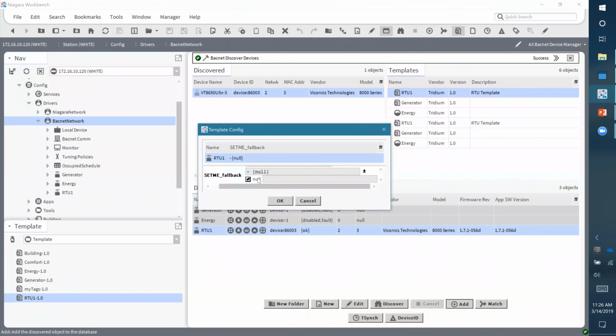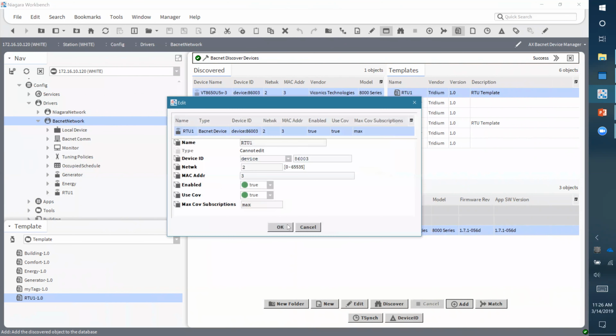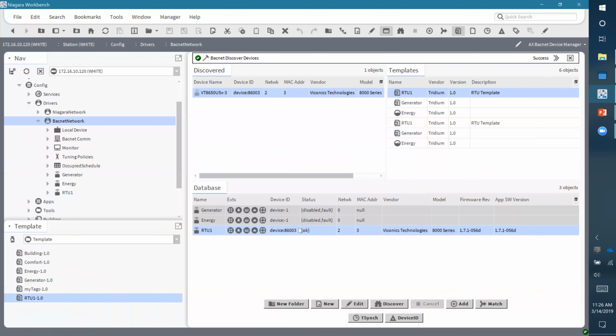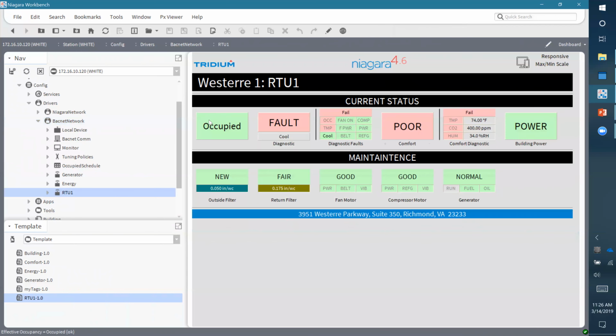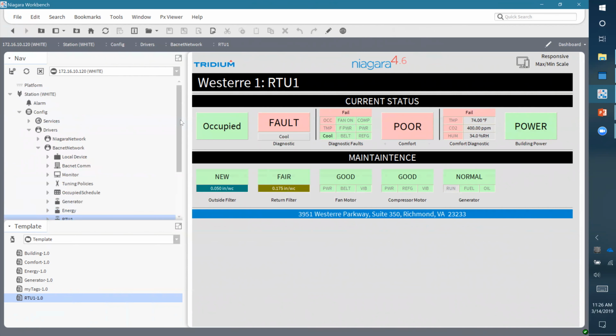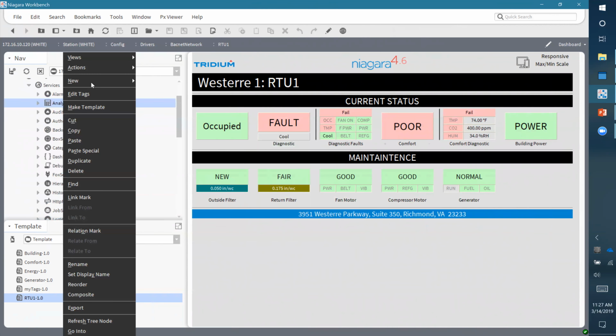It stops. Remember, I said that we need to fill in, this could be set points. So I made this. And now I've set that point inside that RTU, and it's ready to go. So now I have a physical device connected to that JACE that has my entire template. Now I have points or tags that are applied. So I'm going to go over here and go into my services, right? Oops, services, and refresh my analytic cache.